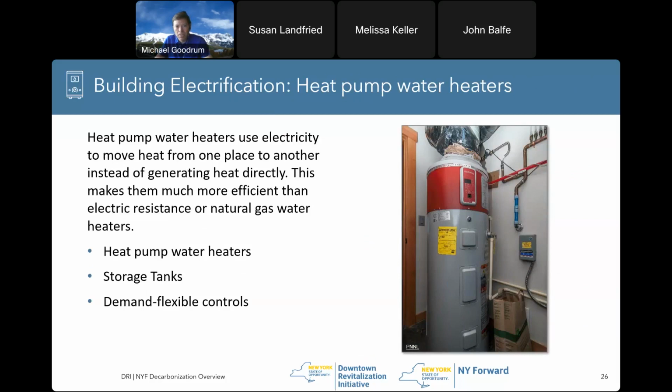So, it's basically just using a heat pump to heat the water. Some things to think about there is with these, you need a proper amount of ventilation. The manufacturer will specify, and that's because it's pulling in the air from the surrounding space to run the heat pump. So you need to make sure you actually do have that space and that proper ventilation.